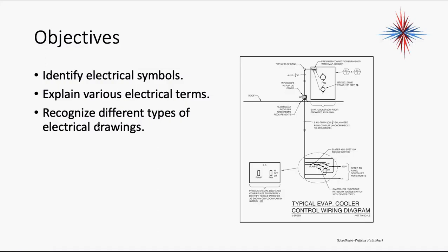This is just an example of what electricians use when we're looking at schematics. Electrician schematics look a little bit different than ours. They're more of the pictorial type rather than the ladder type, because they're all about wiring and wire size and how things are connected to the equipment. We're more concerned about how things are working within the equipment. So again, there are two slightly different types of schematics.